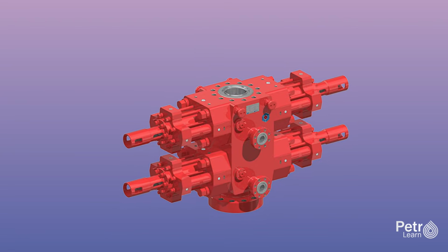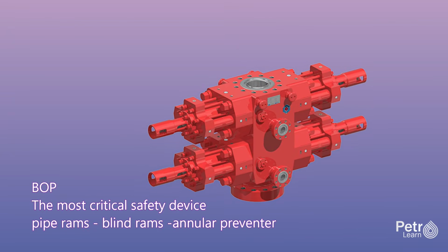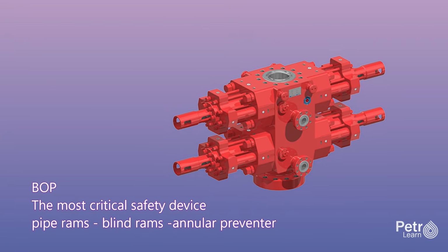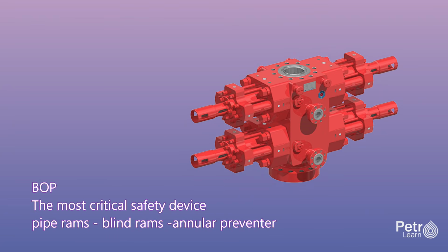The blowout preventer, commonly called the BOP, is perhaps the most critical safety device. This stack of heavy steel valves is installed on the top of the wellbore. A typical BOP stack for land drilling includes several components stacked vertically. At the bottom are pipe rams, which are hydraulically operated steel blocks that can close around drill pipe of specific sizes. Above those are blind rams or blind shear rams, which can close completely and even cut through the drill pipe in an emergency. At the top is an annular preventer, which uses a reinforced rubber donut that can squeeze closed around any size pipe or close completely on an open hole.